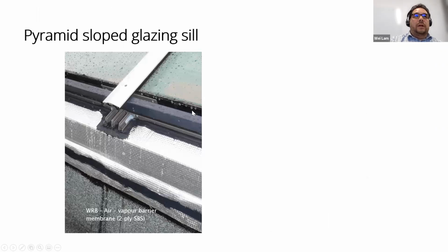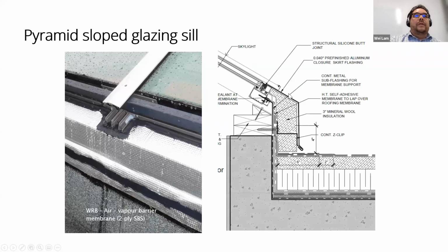So in real life, this is the system. You'll see that the rafter extends quite significantly past that lower purlin, and then this will be closed off with flashings and insulation, exterior insulation, a little Z-girt and cleat here to hold on the flashing.